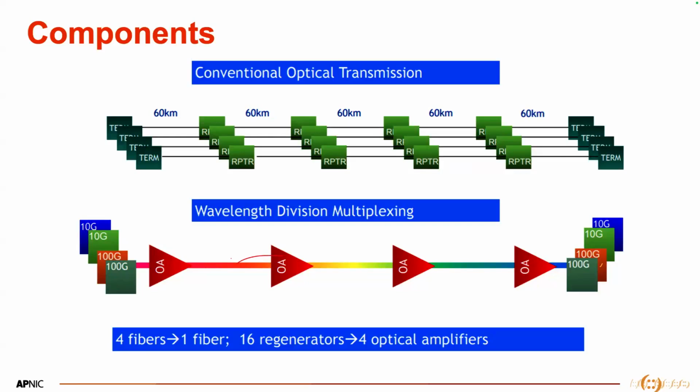But when you use a Raman amplifier, it is happening within the fiber itself. So if it is a 120 km or 180 km fiber, the whole fiber works as an amplifier for the signal because of the SRS effect, stimulated Raman scattering effect.